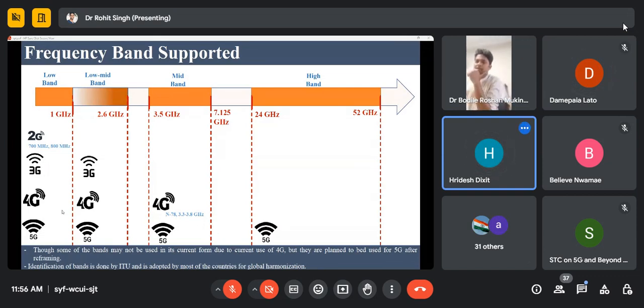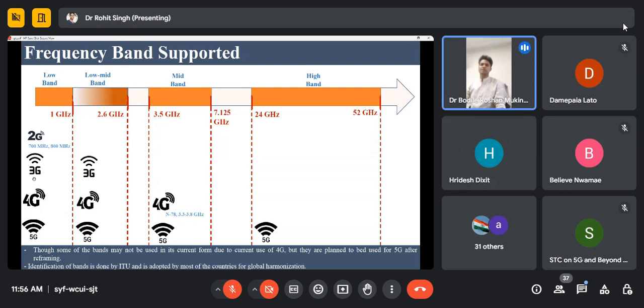For coverage? Yeah. So smaller frequency bands have wider coverage and better reliability of communication. Also, for some low data rate applications, for example, smartwatches and some other industrial applications which require very small data rates, those applications could be supported at these smaller bands. Yeah, so the answer is correct. For such critical applications, we can have the high band. Also, there are some issues with millimeter wave transmission.